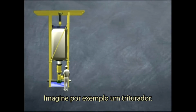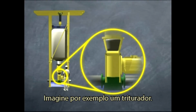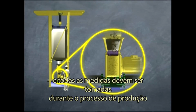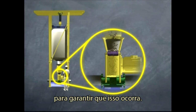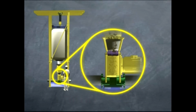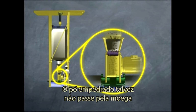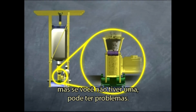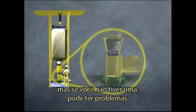Think, for instance, about a so-called lump breaker. Obviously, the powder should be free-flowing, and all measures have been taken in our production process to ensure this. However, if the bags are exposed to heat during transport, or have been transported over rough roads, the powder may have stiffened. Lumpy powder may not pass the dumping station unless this trembling device can be switched on. It may not be used often, but if you don't have it, you can really run into problems.